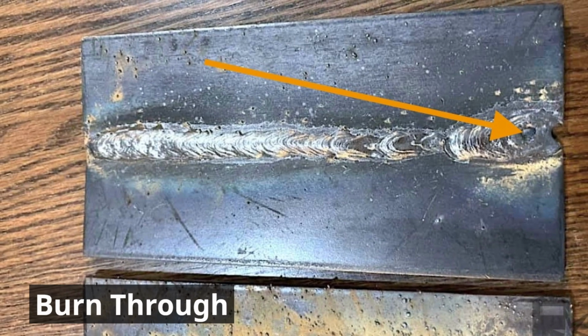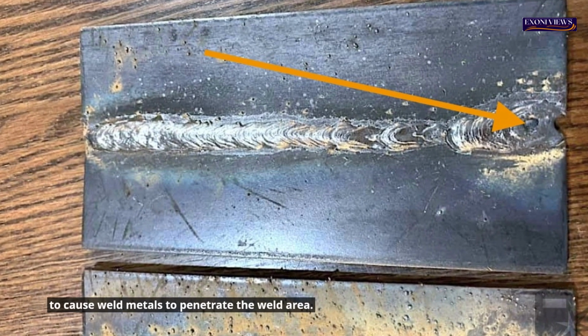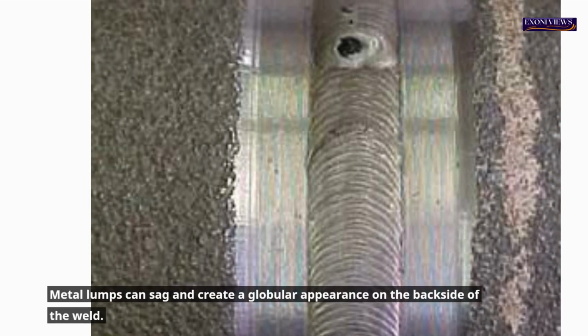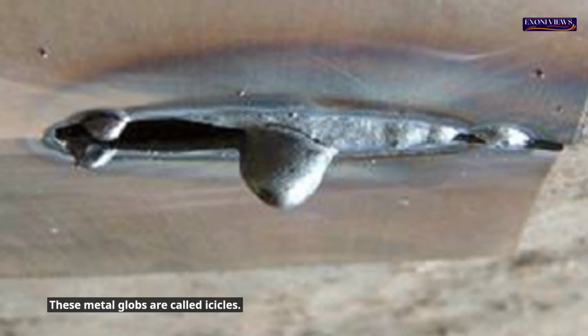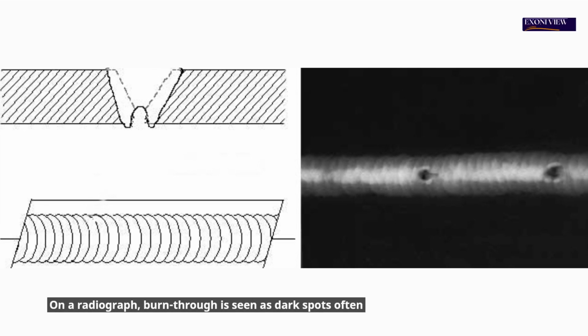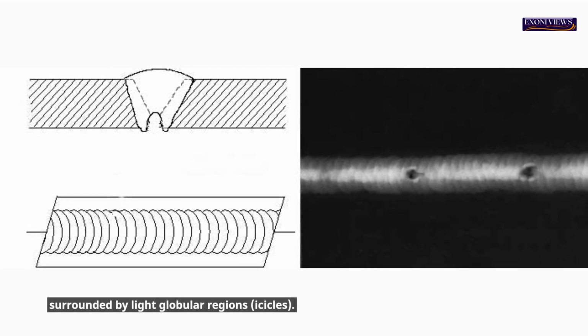Burn through. Burn through occurs when excessive heat causes weld metal to penetrate through the weld area. Metal lumps can sag and create a globular appearance on the backside of the weld. These metal globs are called icicles. On a radiograph, burn through is seen as dark spots often surrounded by light globular regions, the icicles.